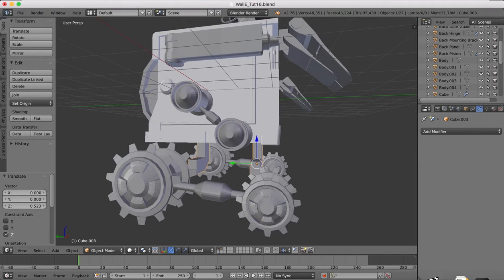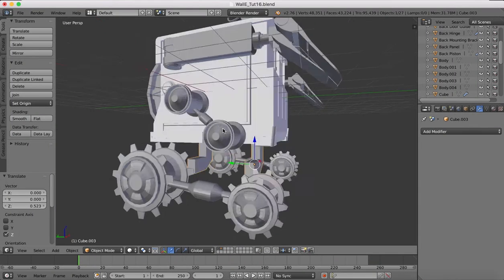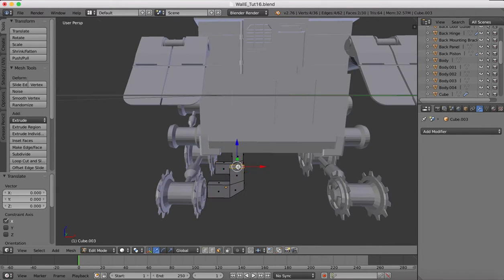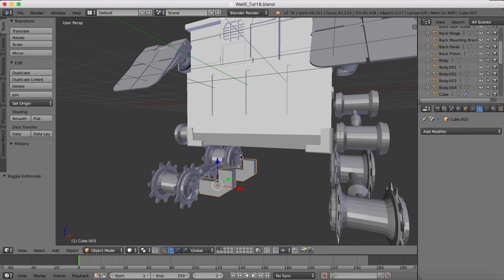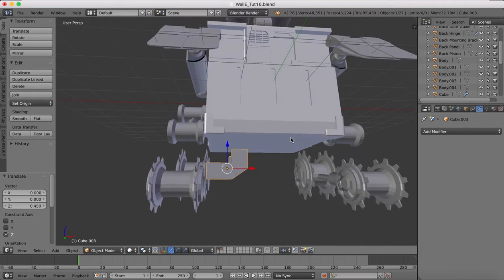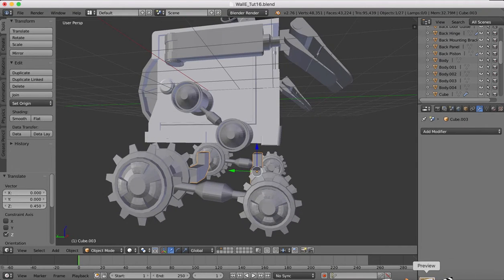And once we've got these in position there, actually bring these top parts down a little bit. So we'll go back over into edit mode, grab the two top faces, we'll bring those down slightly, back into object mode, drag that object up. Okay.